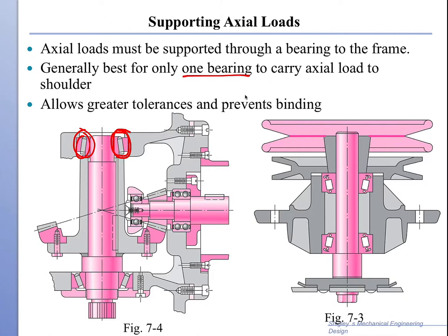You can machine the surfaces so that you have mechanical interlocking around the bearing. So this is mechanically interlocked, and then the shaft is tapered so that it can sit on the bearings, and the bearings are mechanically interlocked here, and everything should be assembled with tolerances. The word tolerances is important to prevent binding of the shaft, so it can actually rotate freely.